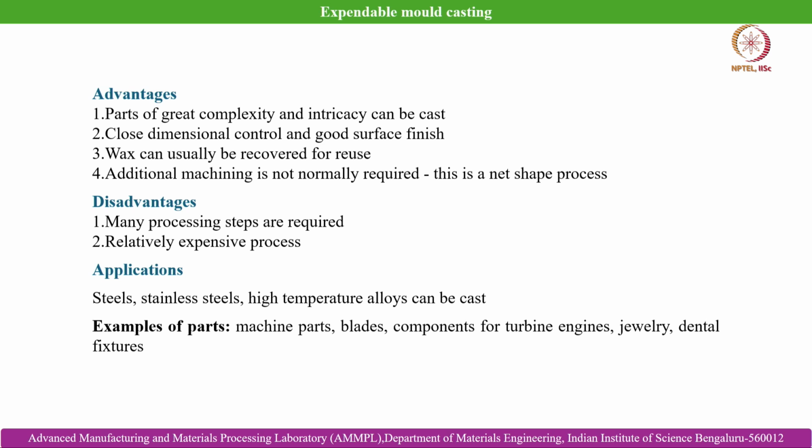However, it is viable only when very high precision is in demand. Otherwise, there are techniques like pressure die casting which can manufacture parts that don't have that much dimensional criticality in much less time, and the casting yield can also be significantly improved in that case.